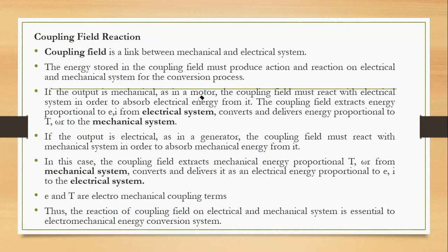First, if we consider the motor case, it converts electrical to mechanical energy. So this coupling field first interacts with the electrical input. After it interacts with the electrical system, it absorbs electrical energy, which is proportional to current and voltage. When we're saying mechanical system, we're considering torque and speed, or angular speed, or velocity.